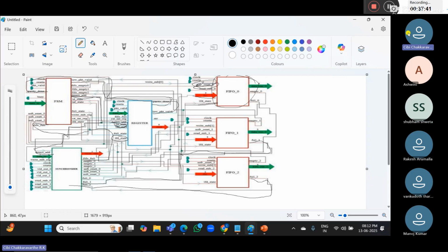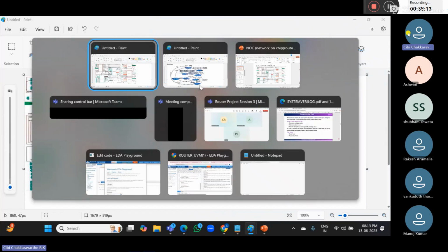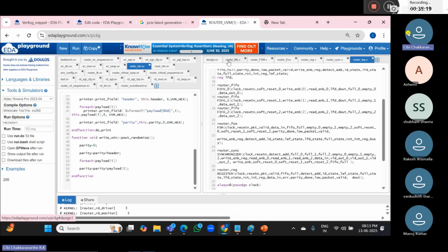Okay. So we may connect it whenever, but instead of making that 0, we are making it to the high impedance state. Why we are making it to the high impedance state in the sense, that signal is there. Actually, there is some data. Our FIFO may get that data, but still it is not responding. So instead of clearing that, we are just disconnecting it temporarily. After it is not permanently having any response from the FIFO, then we can do hard reset. But where we have that information in the sense, we should move to the coding part. Coding part we will discuss separately, but as of our knowledge, we should know.